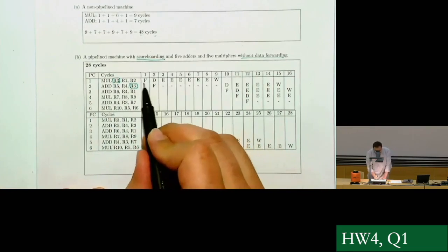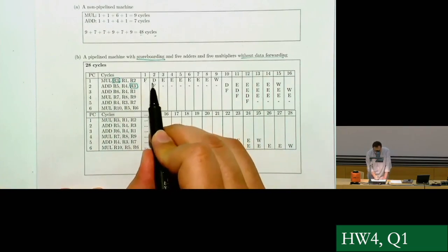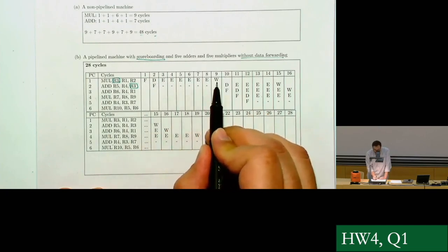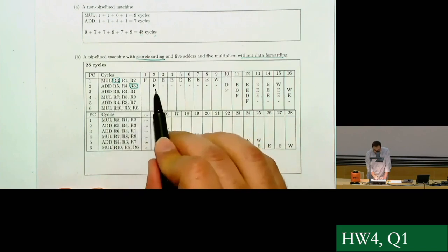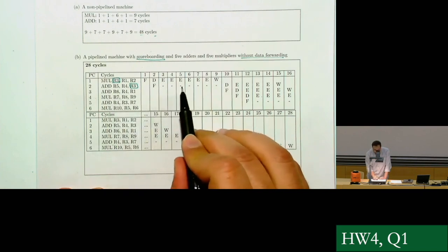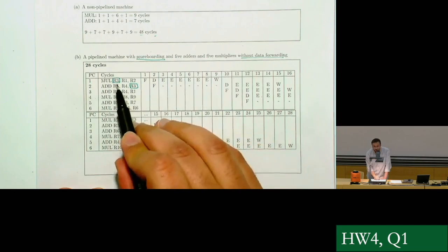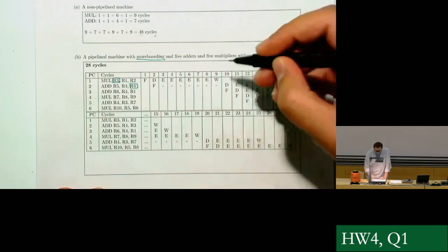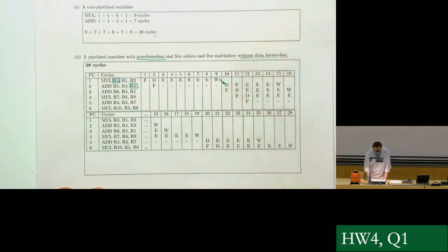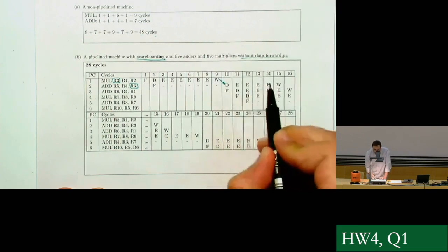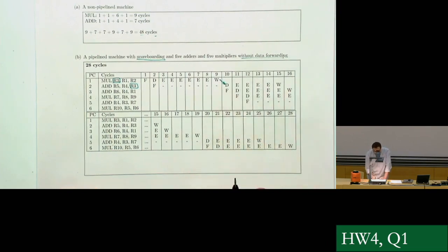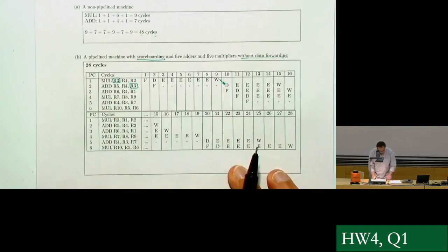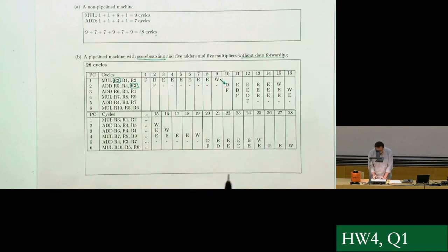As you can see, the mul gets into here, fetch, decode, and then it has 6 cycles of execution and then writes back. And when you have the second instruction, you fetch it, and then you need to wait until the result of R3 is written back to the register file to be able to successfully finish decode. So we have this kind of dependency here. After write back, we decode and then continue, right? And then you just follow the same idea for the other instructions as well.